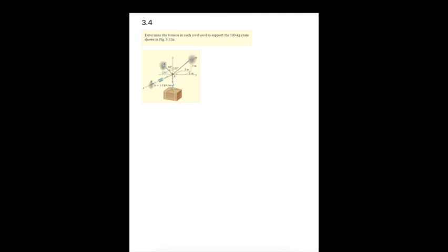So in the last example that we're going to look at in this video, we're going to do this in 3 dimensions. So now we have the x, y, and z directions. The first thing I'll do is my free body diagram at the point A. I know that there's the weight of the crate or the box, which is equal to the mass times the gravitational constant, and that's going downward in the y direction.